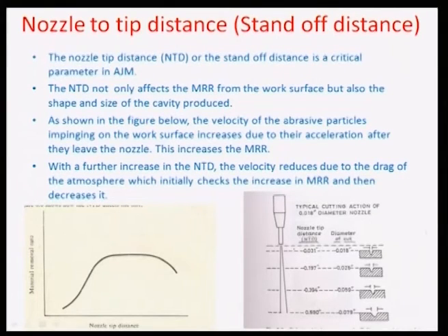In summary, you need to know about the abrasive particles, the selection of that. You need to know about what the carrier gas is and what the composition of this carrier gas is. You also need to know about the operating pressure and the velocity of the gas, and then of course a very important part is also the nozzle from which the jet emanates.